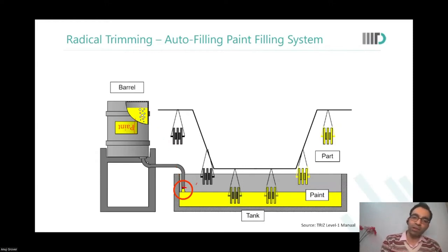The hydraulic pressure that the paint would exert onto the air over here, the depth of this pipe has to be tuned so that the weight of the paint above this height matches the maximum pressure that the air over there will exert. Are you able to see this?